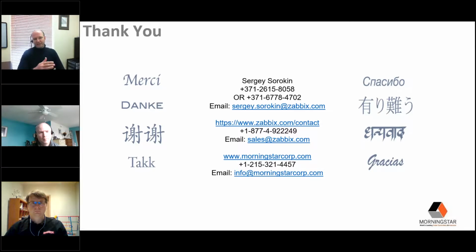But when you get to any kind of a higher level of communication, it's not a server, it's just a PC software program that runs on Windows. When you get to a higher level of connectivity, that's when you really want to make the leap. And that was kind of the impetus for seeking software partners such as Zabbix, because then you can scale to hundreds of thousands of devices and many, many connections simultaneously, depending on bandwidth and server capabilities. So, sorry, long answer, but MS View, I would say 10 to 12 devices, maybe 20 pieces of data from each controller. Anything greater than that, and you're going to want to look for a more scalable third-party solution.